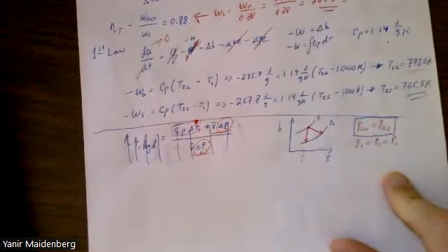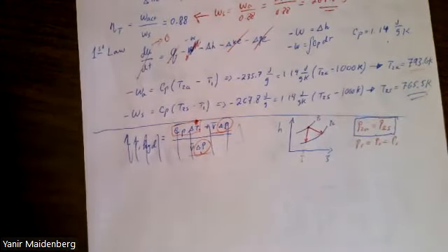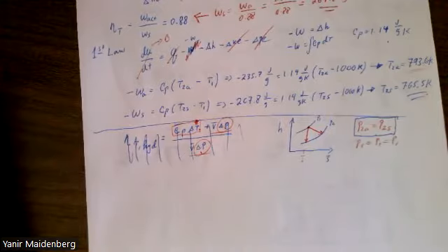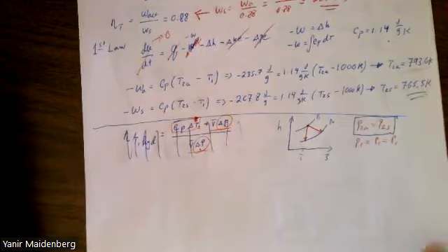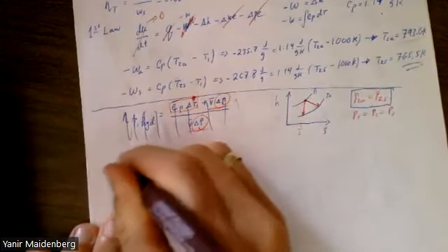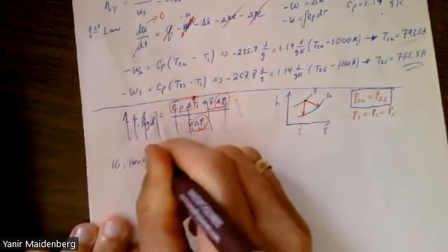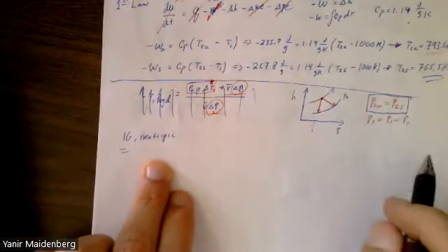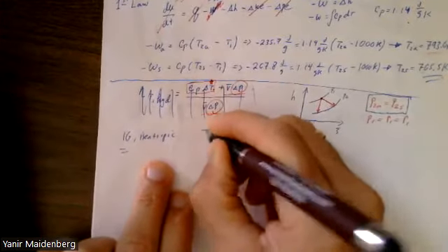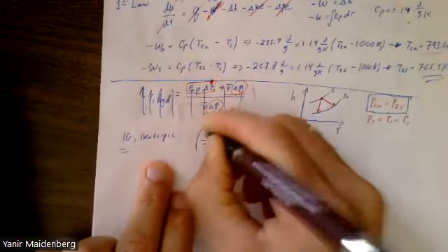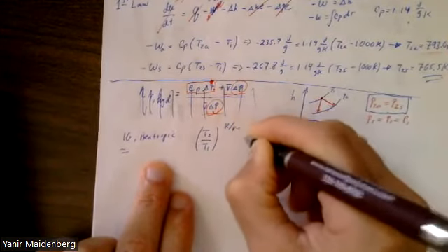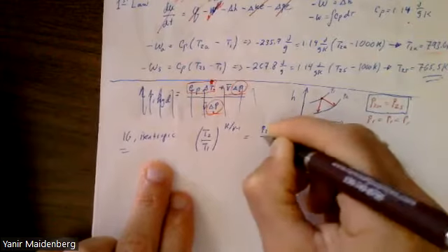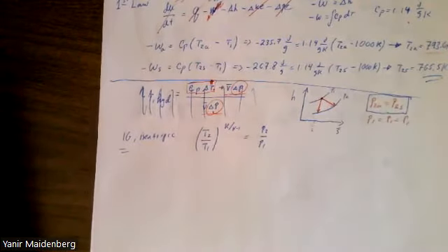Okay, so we're going to look at the isentropic condition, and it gives us an equation between the temperatures and the pressures for an ideal gas. So for an ideal gas, isentropic, we're not making any new assumptions. We said it's ideal gas. We know it's isentropic for the reversible process. We know that T2 over T1 raised to the K minus 1 over K is going to be equal to P2 over P1. And again, P2, no matter what it is, is the same for both scenarios.